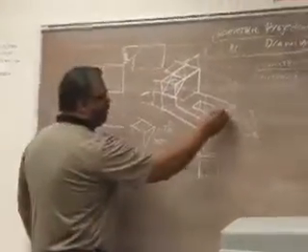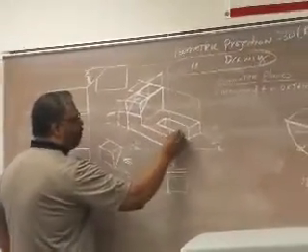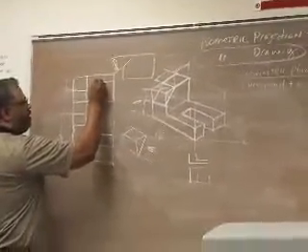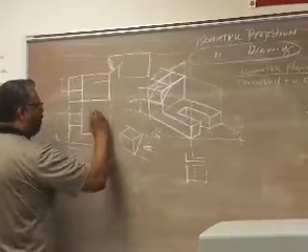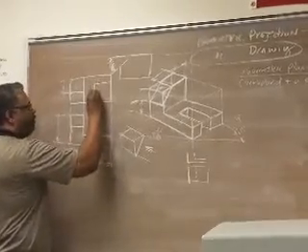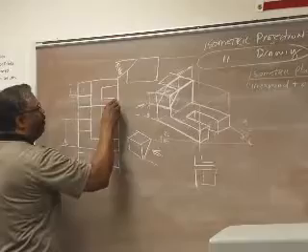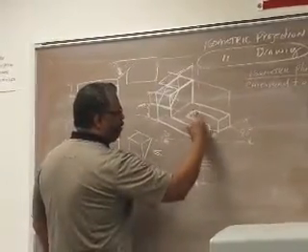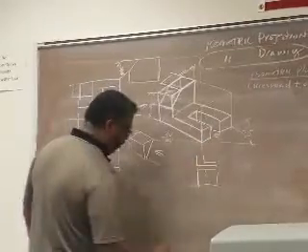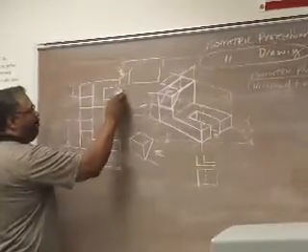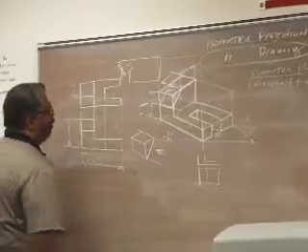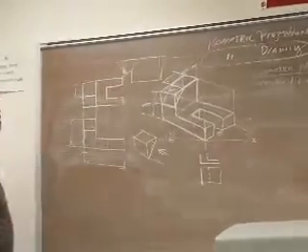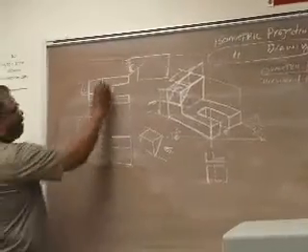Well, we pick up this outline right here as well, so there's going to be a cut in here, and whatever we do, that should match that, because that's where that edge came from. So if we say that's our cut, then we cut all the way back, there's material here, but there's no material here, so this edge goes away. So now we have the top view of this object right there. Now we have the top and the front.